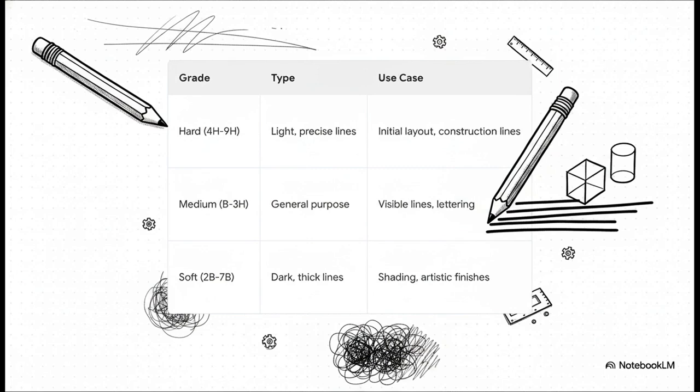Even the pencil becomes a highly specialized instrument here. Picking the right pencil grade is absolutely crucial. You'd use a hard pencil, like a 4H, for really faint construction lines that you could barely even see. Then you'd switch over to a medium HB for the final, bold lines of the object and all the lettering. Using different grades is what gave the drawing its depth and clarity.